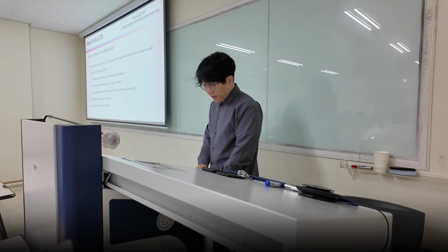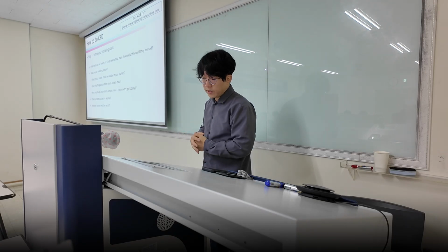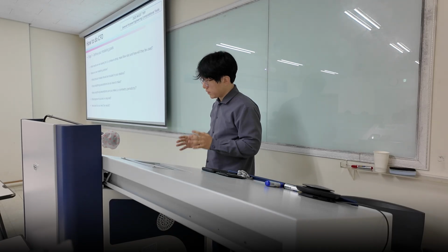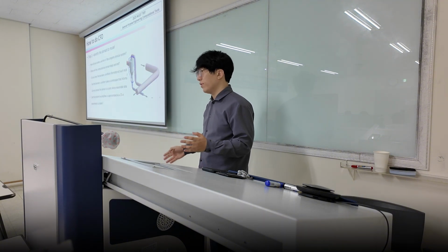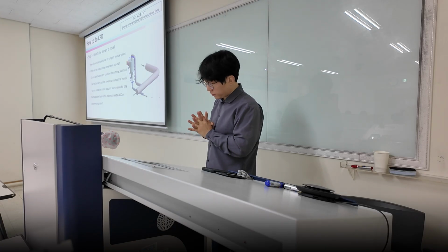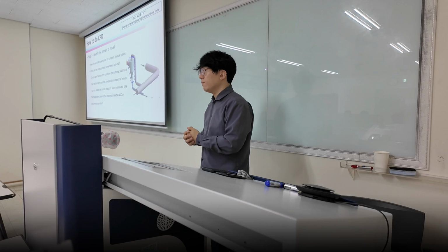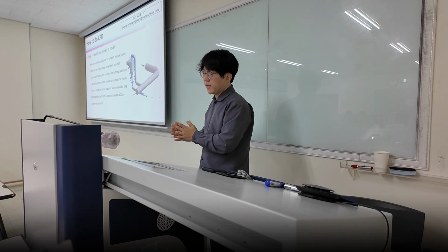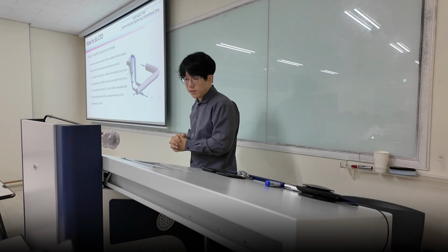And also there are simplifying assumptions. You can use symmetry and periodicity. It's really, really important. And this is also tightly related to the CAD tools we learned in previous lectures. You have to define the domain properly, you have to understand the phenomena, and then you're going to take out the 3D model from the domain and then isolate it with proper boundary conditions.